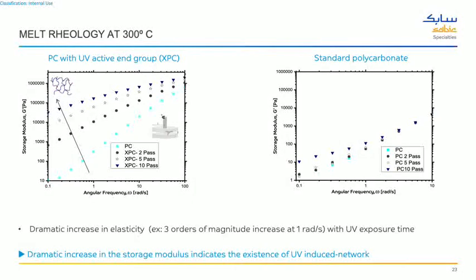So I made a part, I expose UV light, then you do this test in a solid state like DMA, where you can see storage modulus as a function of temperature. You can see a linear polycarbonate, for a given molecular weight, has a decent Tg around 145, 150, and then has a plateau, and then the modulus drops and the structure goes away and it's in melt state.